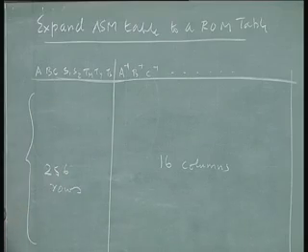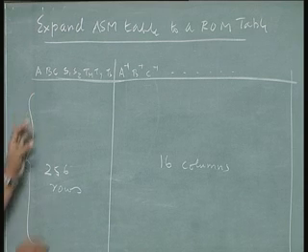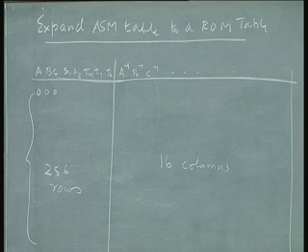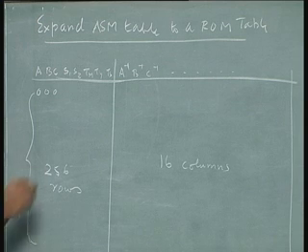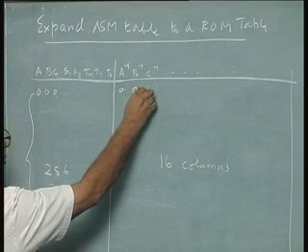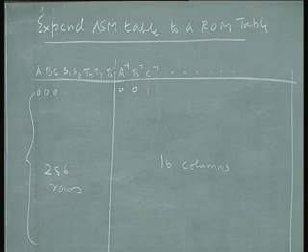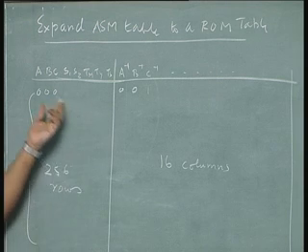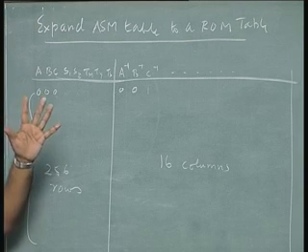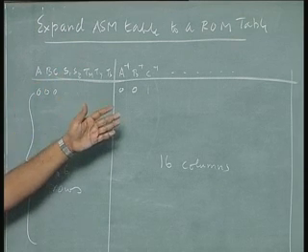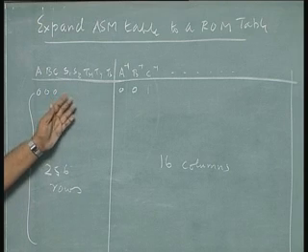But the ASM table has to be expanded. For example, the 0 0 0 state, whatever is the condition, goes to the next state 0 0 1. I am just telling from memory, please refer back to your notes. In state S0 there is no condition, you always go to 0 0 1. And what is the output in the state?